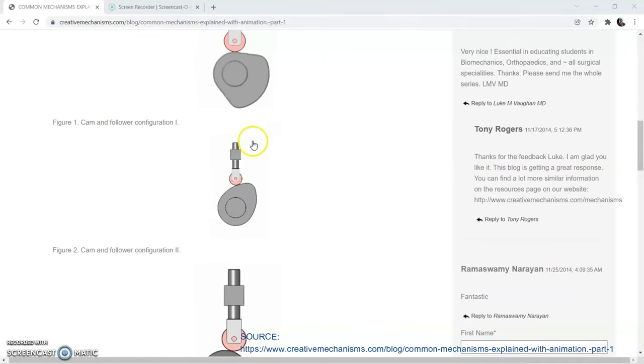So on this topic, we will be drawing what we call a displacement diagram and a cam profile. A displacement diagram is the path that we want the cam follower to take. And that displacement diagram we will then use to construct, or to find, what shape the cam profile will be for us to achieve the motion that we want the cam follower to follow.